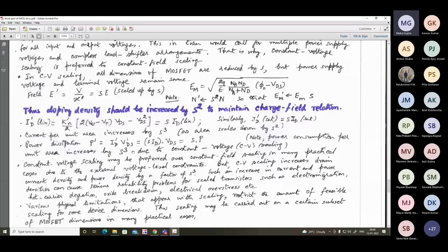But we have to progress over technology. We have to progress over the need of the day. So some mechanisms have been brought in to control this, but we cannot totally eliminate it. That means hot carrier degradation, oxide breakdown, electromigration, all will be present. So we have to limit the current to some extent, and take care that the current does not go past a particular limit. Also, we have to keep watch on the value of the maximum field that the designed circuit is subjected to. Keeping all this in purview, we need to take action.